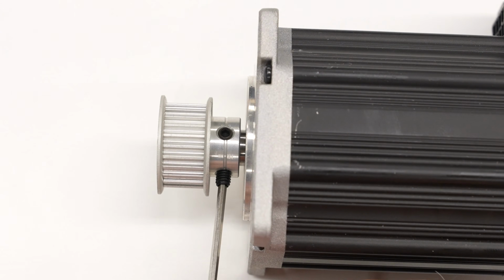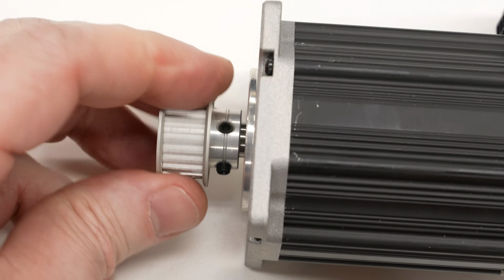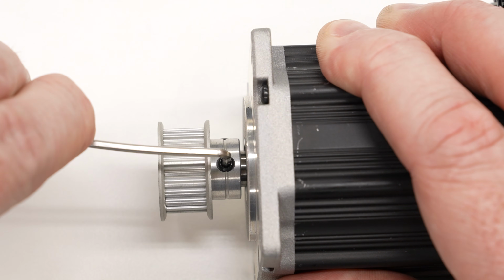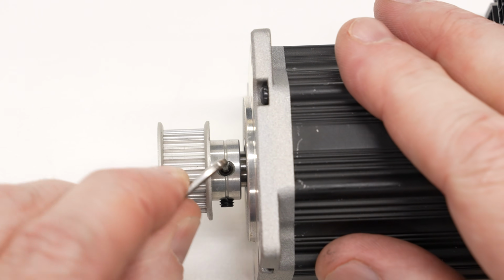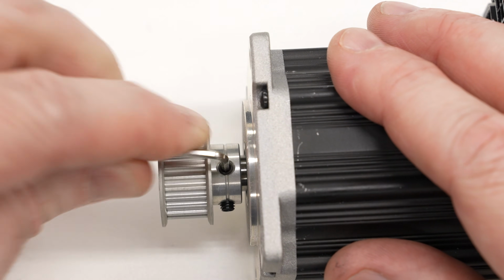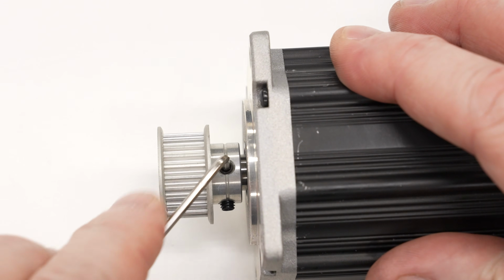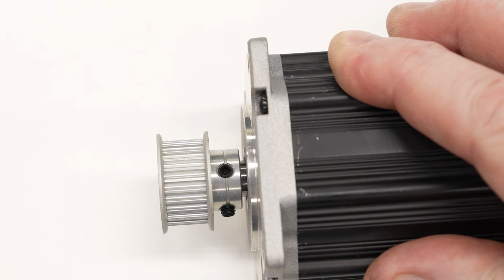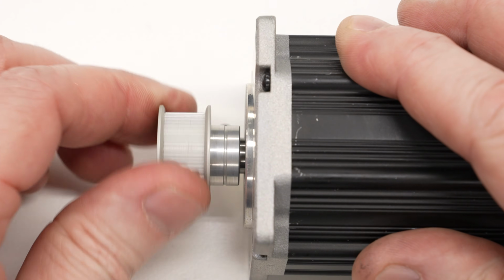Snug that down, put in the other screw, and then we'll put some torque on both of these to make sure they're biting in well and this isn't going to move at all on the shaft. If it does, it's going to reduce the accuracy of the machine, and it's ultimately going to wear on the shaft, and we definitely don't want that. When I put this together for the last time, I'll probably mark the pulley and the shaft with a paint pen just so I can make sure that over time it doesn't shift at all.